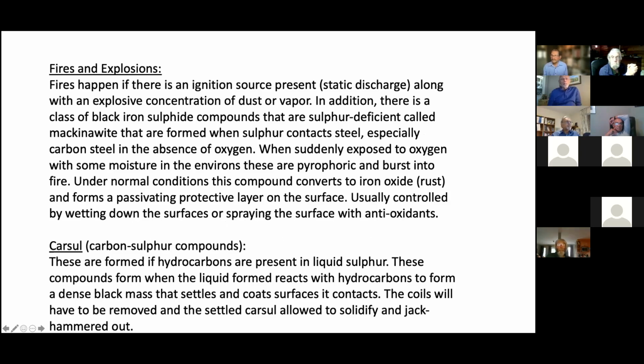Then fires and explosions. Like I mentioned before, you can have static discharges. Typically, when you drop sulfur from a height in dry air, or even liquid sulfur when it's flowing at a high velocity, say, for example, you're pumping into a pit and there's a large drop, you can have static. And I've seen explosions and fires in pits set off by static discharge. If you are not careful, you have to make sure that, first of all, you design so that you don't have these drops, and all the equipment, anything dealing with sulfur, liquid or solid, is properly grounded, bonded, all that good stuff. Very important. I've seen major towers blow up where they've dropped sulfur through heights, both liquid and solid. Sometimes, even loading rail cars where they don't have telescoping chutes dropping down, and they drop from large heights, you can have fires or pops.